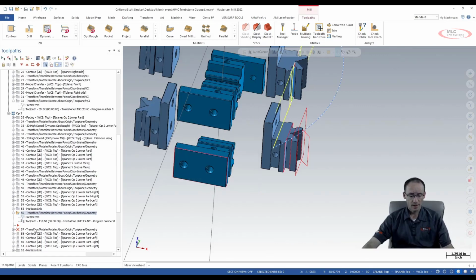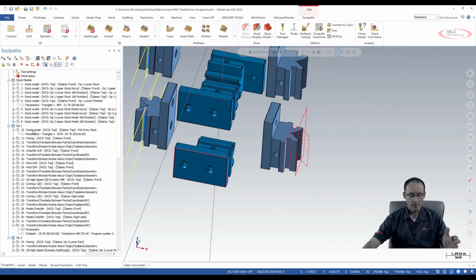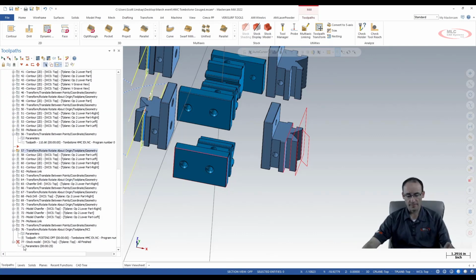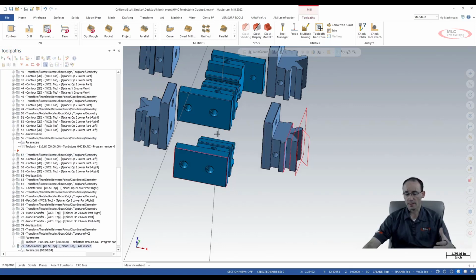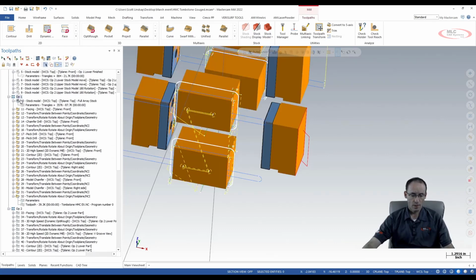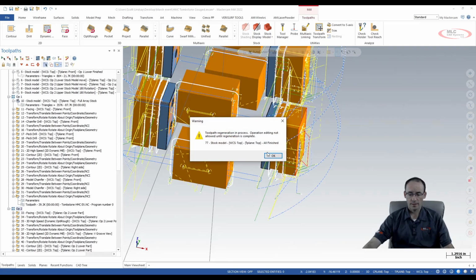It's going to generate. I'll generate this one, and that's going to dirty a stock model at the bottom that I have that shows me all of it done. So I need to regen that one so I can get a screenshot of what it looks like without going into verify. And we'll pick all of block 1 and all of block 2, and go into our verify.